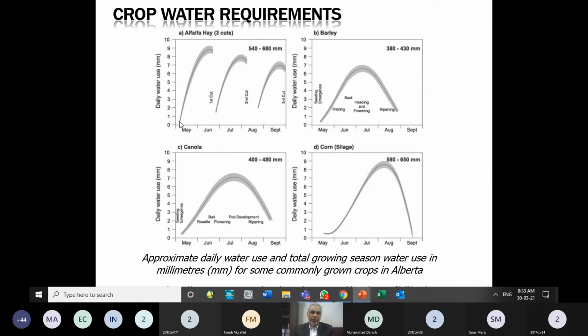So for that, if you see the crop water requirement on a daily basis, because when we define the crop water requirement, we can mention it for different periods of time. Somebody can measure it for one day. Somebody can add the crop water requirement for the whole crop period. So if I add the daily crop water requirement, it will give me the total crop water requirement. If we add the crop water requirement for the whole base period, for the whole crop period, then another name is used for that. We call it delta of the water which is required by the crop.